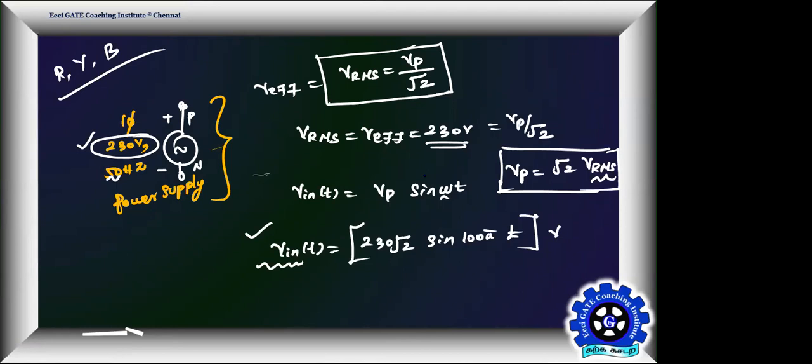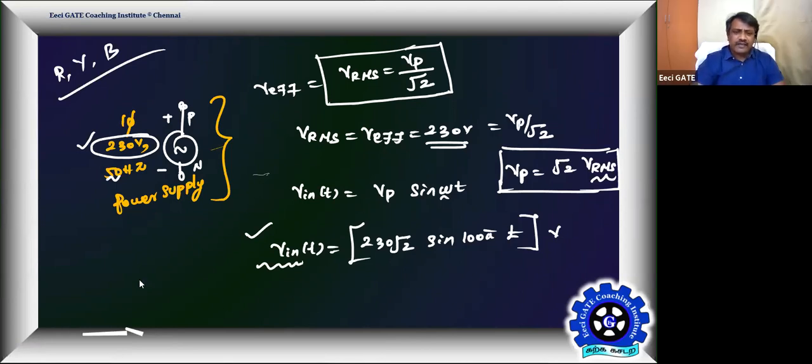Okay, we'll go ahead. So the important point is, why do we have a convention of an AC source being referred to by its effective value? That is nothing but our well-known root mean square value. Square means squared average. A normal average doesn't exist for a pure sinusoid, so we go for the squared mean or squared average, then apply the root.